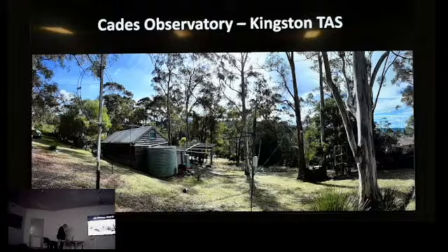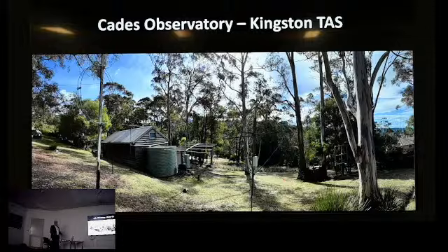You can see I've got lots of trees, and I did start off by chucking up lots of wires and being a bit like Grote Reber. Grote had a massive array at Bothwell. He would climb poles, and I guess at the low frequencies you need big antennas essentially. You've got to get something close to a wavelength or half a wavelength. I'm operating in a range where a wavelength is maybe 10 meters, and half a wavelength, which is usually what you need to pick up something, is 5 meters. So even that's getting a bit long.